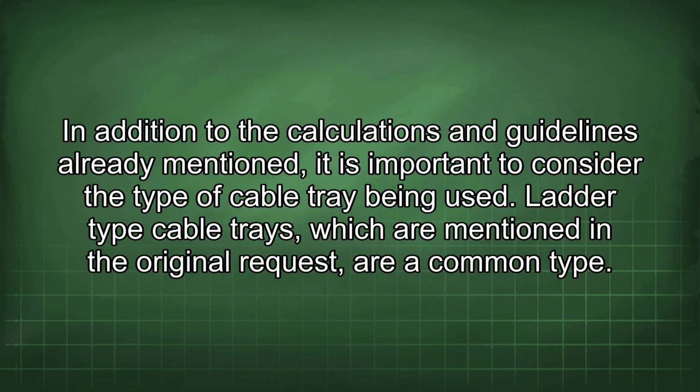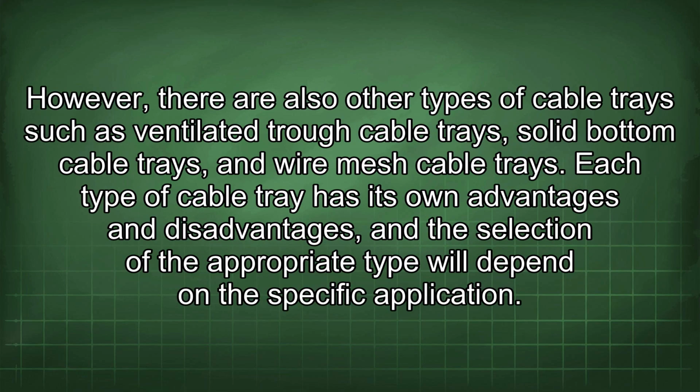In addition to the calculations and guidelines already mentioned, it is important to consider the type of cable tray being used. Ladder-type cable trays, which are mentioned in the original request, are a common type. However, there are also other types of cable trays such as ventilated trough cable trays, solid bottom cable trays, and wire mesh cable trays. Each type of cable tray has its own advantages and disadvantages, and the selection of the appropriate type will depend on the specific application.